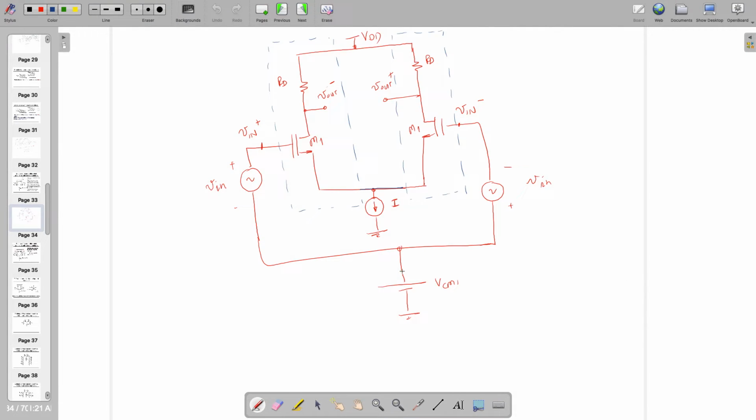If you look at this one, and let's call this ISS as named in Behzad Razavi, the output common mode voltage is depending not only on the input common mode voltage, but no matter what input common mode voltage VCMI you are giving over here, the output common mode voltage is depending on the current flowing through the branches and the GM offered by M1, right? So this is very important.